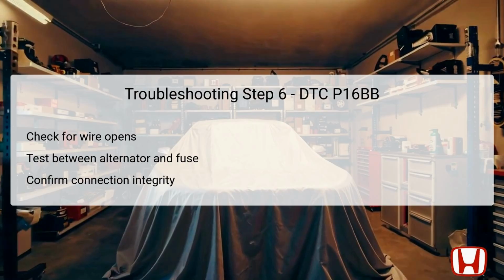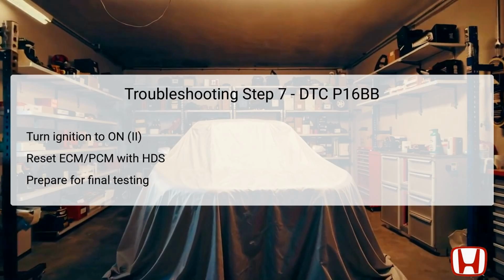If the wiring continuity test yields a successful result, it indicates that the harness is likely functional and should not impede voltage output. Conversely, any open circuits found would necessitate focused repair efforts to restore the circuit path's integrity before moving on. After assessing the wiring, we now return to resetting the engine control module (ECM), or powertrain control module (PCM), to evict any persisted codes.